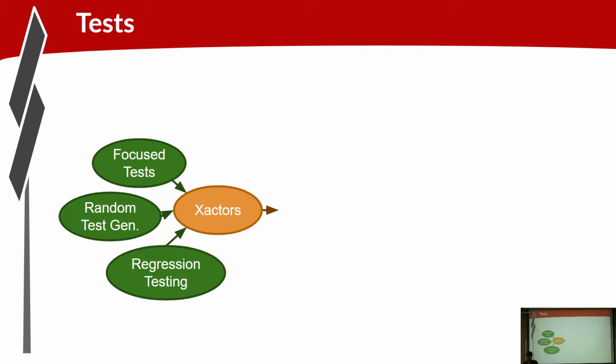Let's drill a little bit into tests. So the transactor, of course, is driving the tests into the DUT. We have different types of tests that would drive that DUT. So we have a focus test. In the case of a CPU, that would be a program, right? It's doing one specific thing, trying to exercise very specific scenarios.